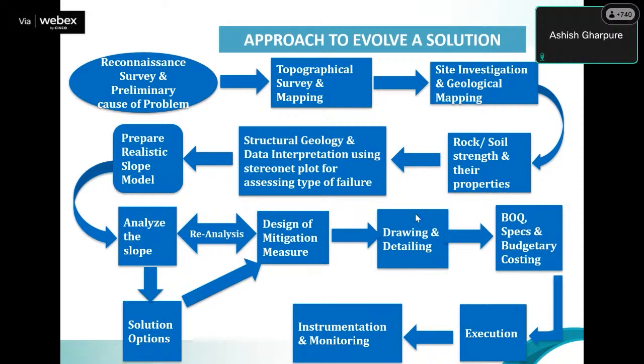The factor of safety minimum recommended for seismic cases is 1 and for static 1.3, and whether we are attaining those has to be discussed and arrived at for each location, because at every location there are some local issues, or you can take help of local workers or practices. So we can localize the solution. We obviously are interested in giving detailed drawings so that it can be adopted at site, bill of quantity, specification, budgetary costing, and then go for execution.